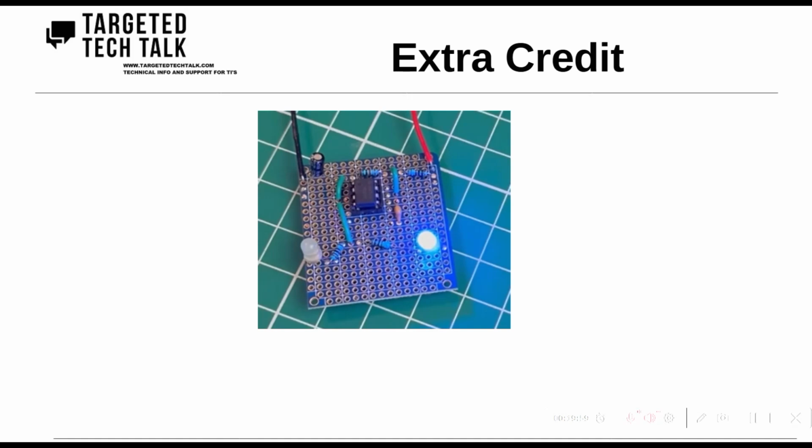It's got a copper substrate with those little holes that you can see, and then you solder in the components to each of those, and on both the front and the back side, you can make the connections. This one is dual-sided that we're looking at. So you can make the wiring connections, and then this would be a permanent style project. If we look at taking what I did with the breadboard and want to upgrade that to a permanent and mobile solution, we could use a printed circuit board, which is this kind of design.